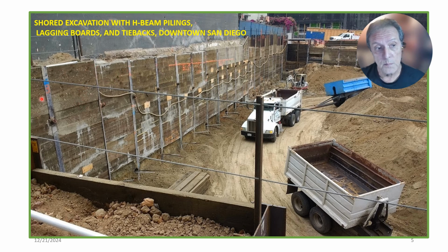As they go down, they put these wooden lagging boards in between the pilings to provide stability as they excavate down. And when they reach completed depth, these pilings will remain. But as an interesting sideline, geologists are called upon in downtown San Diego to log or map the sidewalls of the excavation as the excavation is being brought down.